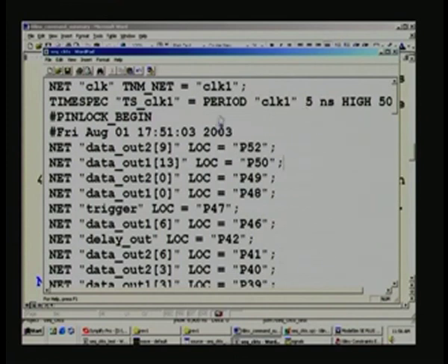You can even edit a UCF file, or create your own file on similar lines, and you can straight away run it right at the beginning. You could have given that .ucf file at that point of time, then it would have taken all the pins with your mapping, and your choice would get affected.